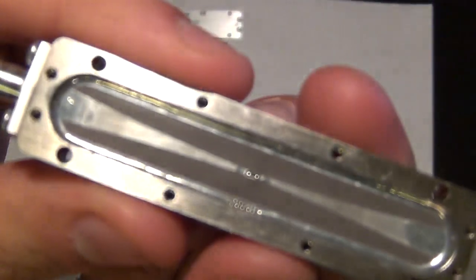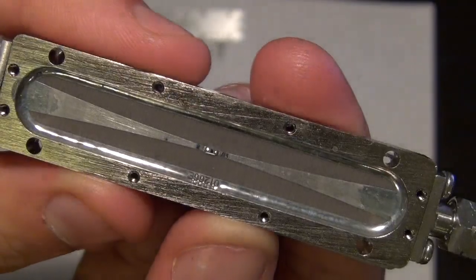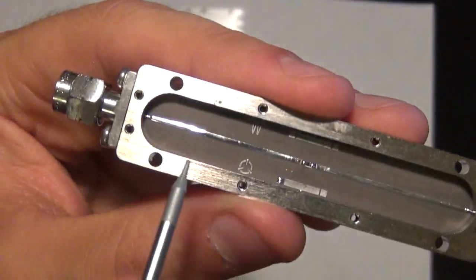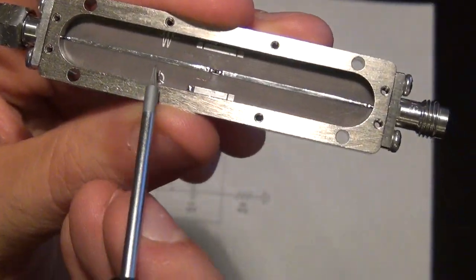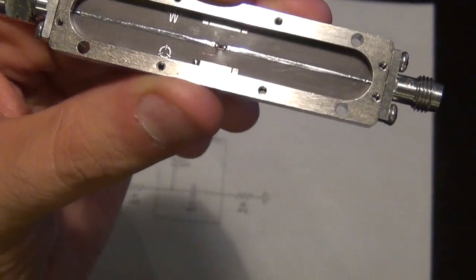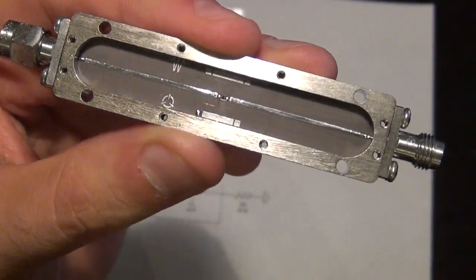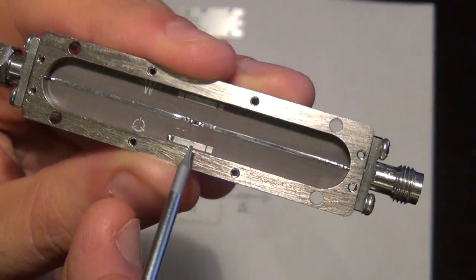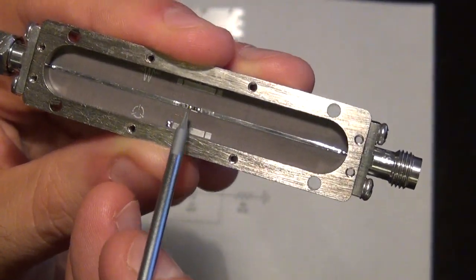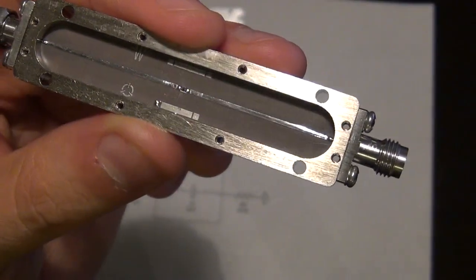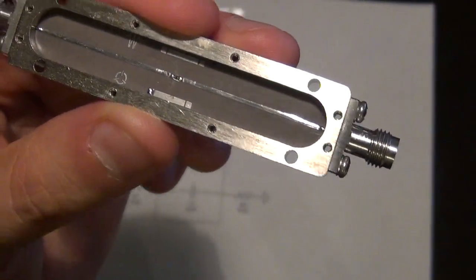So in the center of this, you can see a tiny little diode there, and on this side, you can see the signal path. So let me show you carefully. The signal comes in here, and it reaches the diode. The diode will rectify the signal and create a second harmonic. And you see this tiny, tiny little copper wire? That's actually a filter. Someone measured that distance and the length to filter out the signal and isolate the output to be twice the frequency.